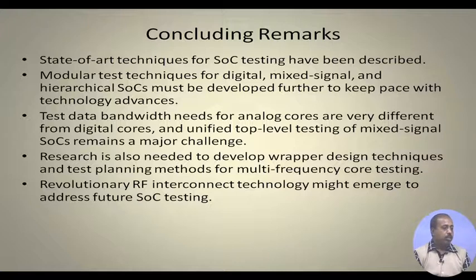Coming to the concluding remarks. State of the art techniques for SoC testing we have seen. We have seen that modular test techniques for digital cores can be developed so that they can be integrated with this SoC testing mechanism. Test data bandwidth needs for analog cores are very different from digital cores, and unified top level testing of mixed signal SoCs remains a major challenge. As I said, analog testing is a challenge, and that continues here also.